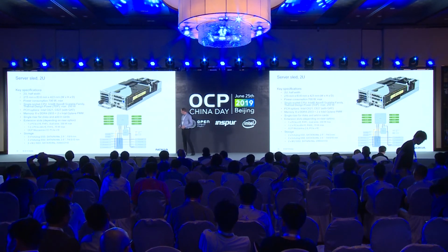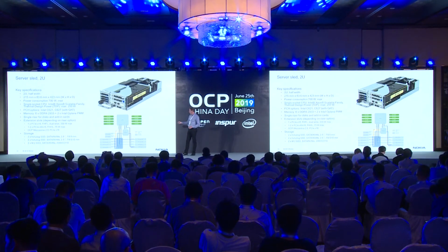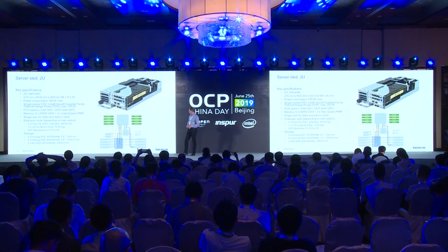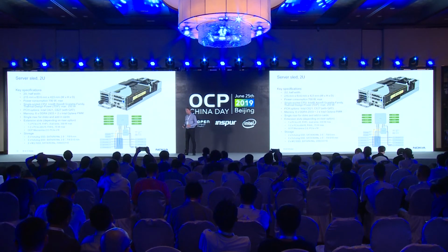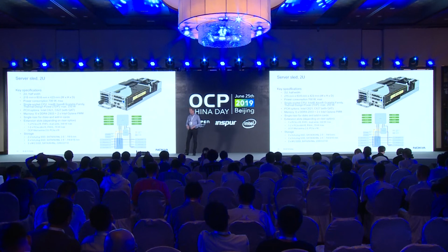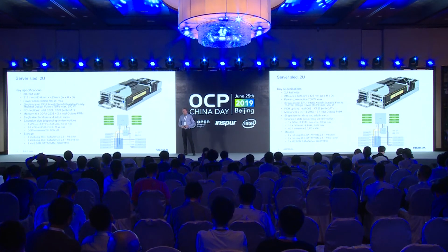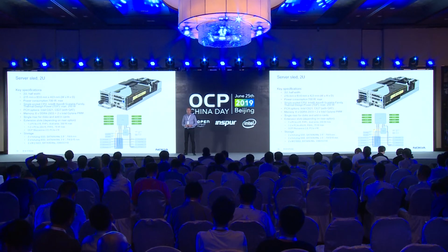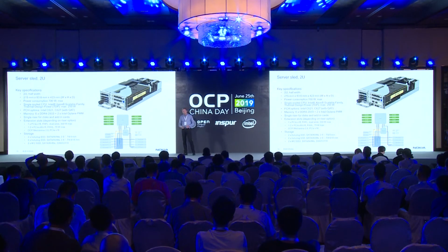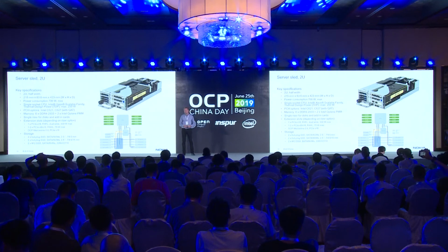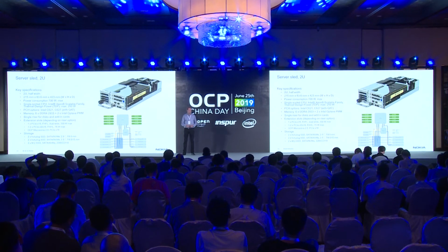And same thing for the 2U server. The blue box here is the riser card, and all the PCIe and SATA interfaces are routed via that riser. So the connectivity can be redefined by redesigning the riser card. This is sometimes needed when there's a limited amount of PCIe lanes, which is the case with the current Intel Xeon CPUs, especially with a one-socket server.